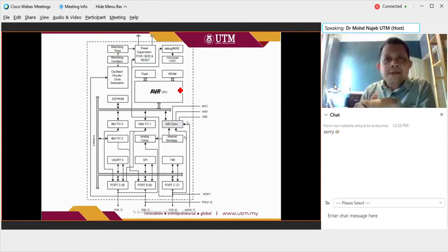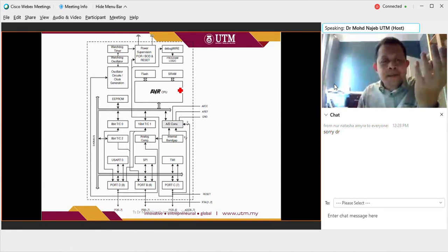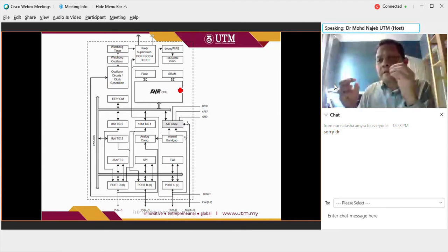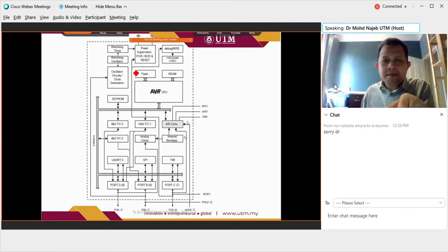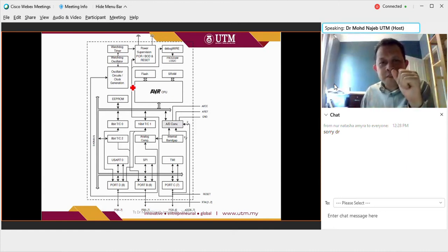So what will happen, right? When the drone receives those bursts of electromagnetic waves, let's say for example the clock or the timer might malfunction, right? It might get lost. The data inside might just reset and get lost, right? So what happens is the watchdog will disable the reset of the microprocessor, and after some time it will turn on back, and it will see if the clock is still working, right? If it does not work, it will stop, right?